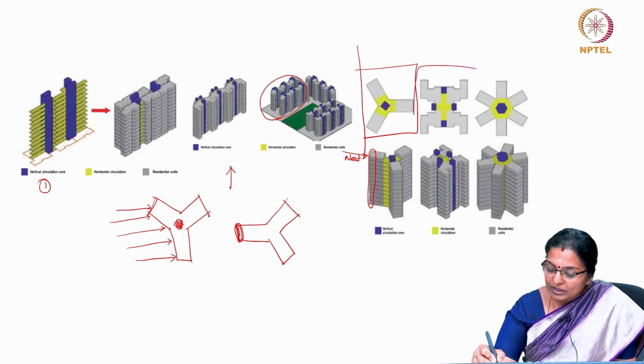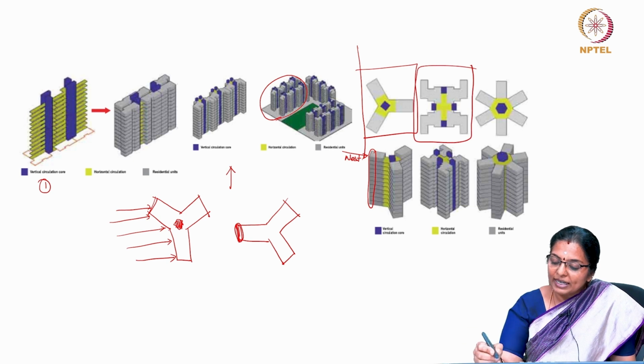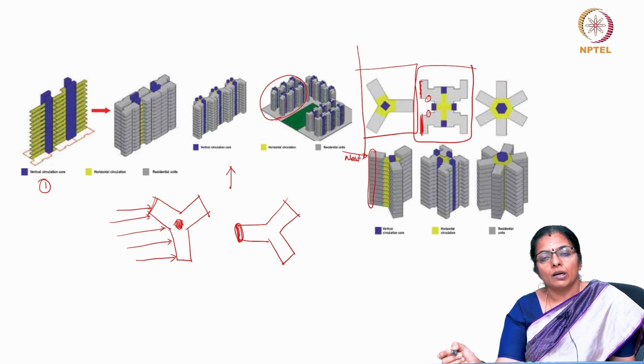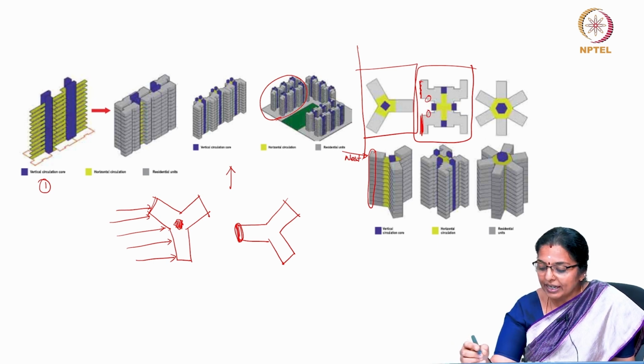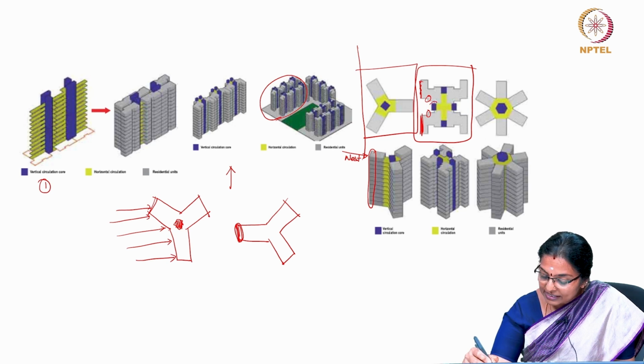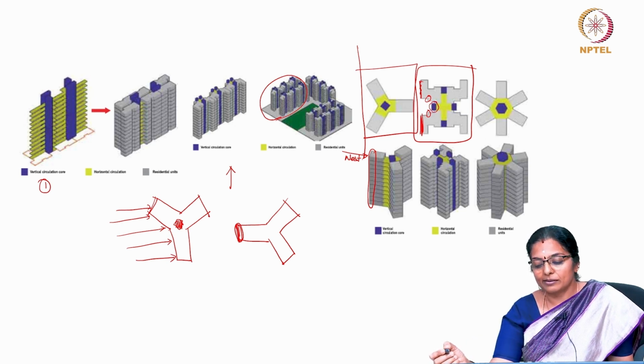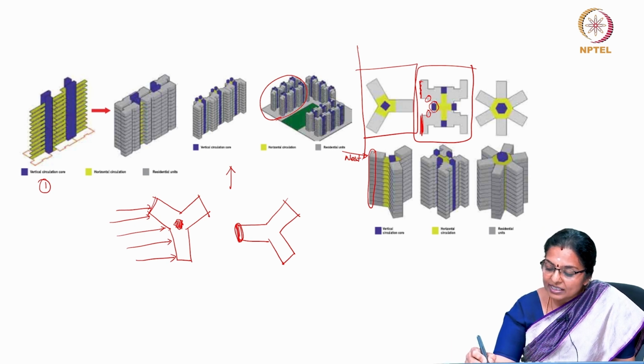Again, when you come to this design, you can see that these surfaces are completely exposed. These surfaces can be saved due to mutual shading, whereas this is a vertical tower and it is a non-habitable space, though these houses will be subjected to extreme heat.